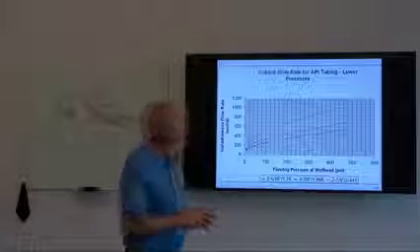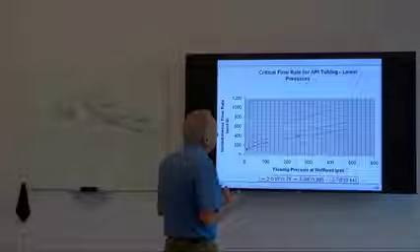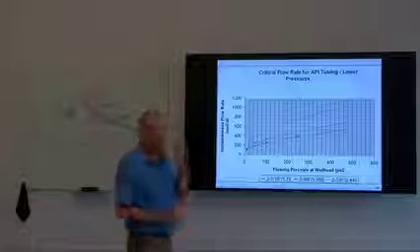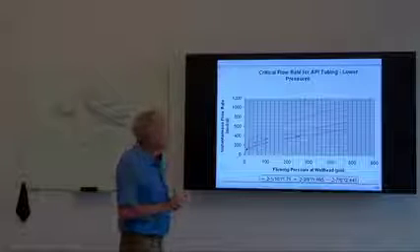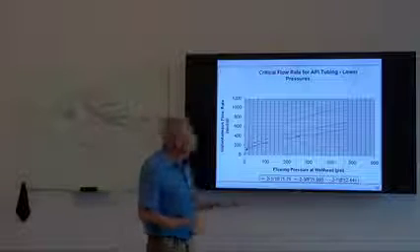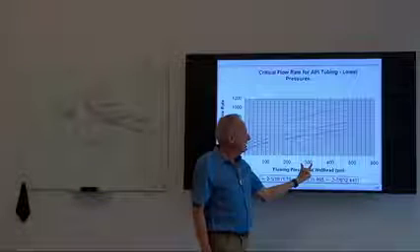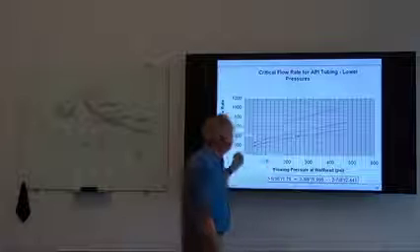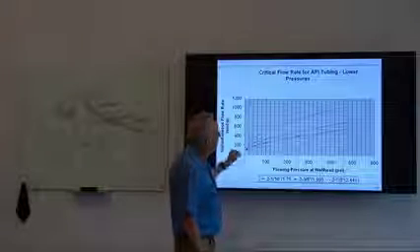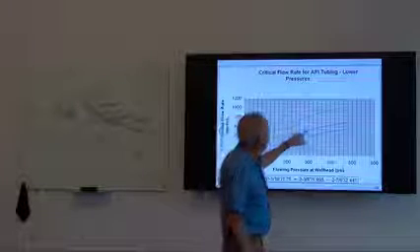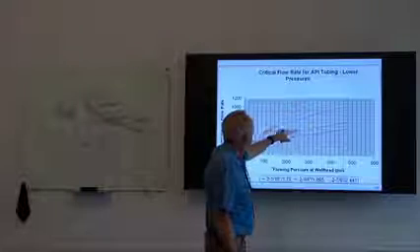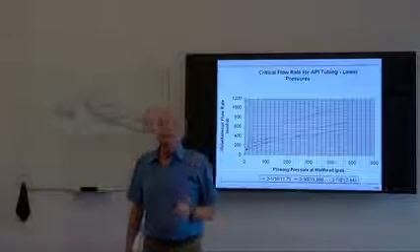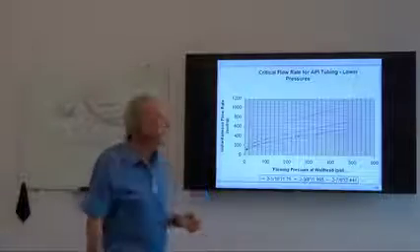And critical rate, as calculated by Turner, and this is just a set of typical curves that we've seen in use for many, many years, where folks would look at what their pressure was at the wellhead. In this case, let's take 300 psi, and let's just say I have 2 3/8 tubing, which is represented by this line, and it says that I have a critical rate of about 550 MCF a day.